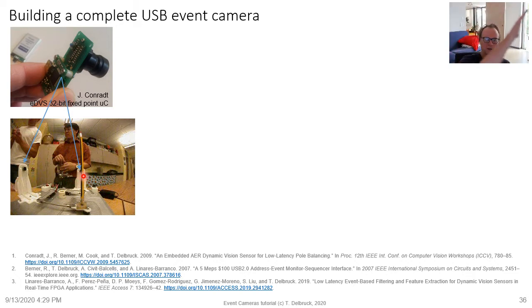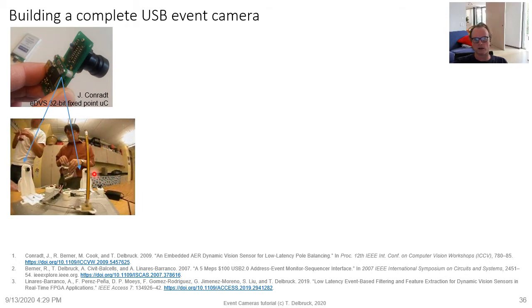And so once you know from those two positions the angle of the pencil and the position of the pencil, you can use an algorithm, a beautiful continuous, non-discretized Hough-based transform, to extract the angle and position of the pencil from these two right-angle views and develop a controller which runs on another 32-bit microcontroller here that controls this arm. And you can see that running here.